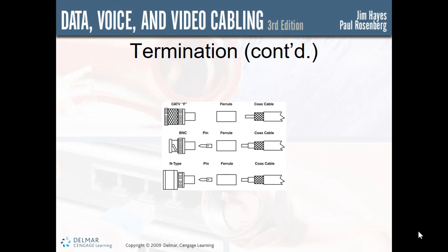For example, connecting your VCRs using simple screw-on F connectors. For building wire and coax, especially for CATV, we need to be more careful to ensure high performance and low signal leakage. Compression connectors are preferred, and cables should be of top quality. When making up a coax connector, it is important to make sure that the connector type matches the cable type and that the connection is made up securely.